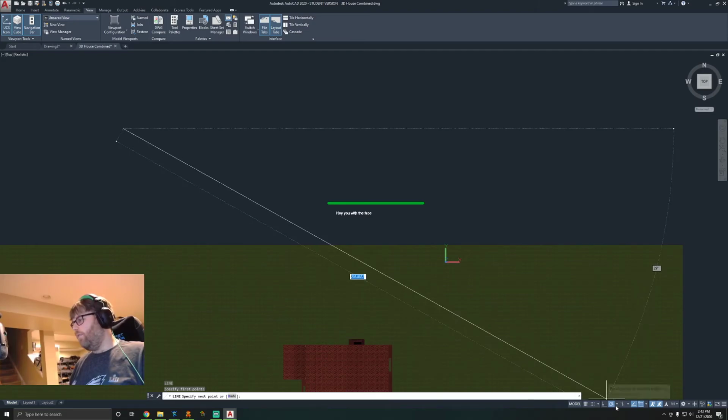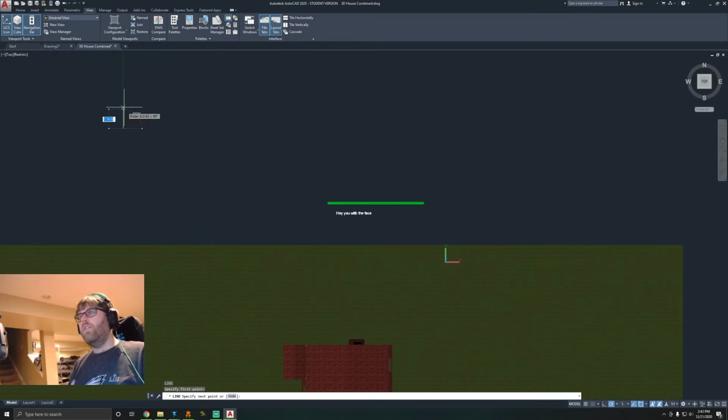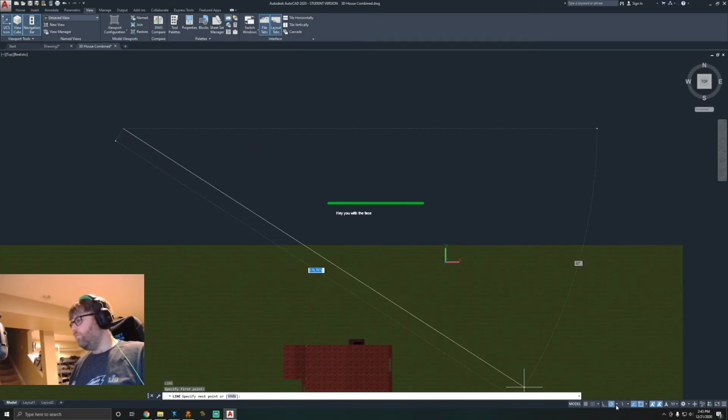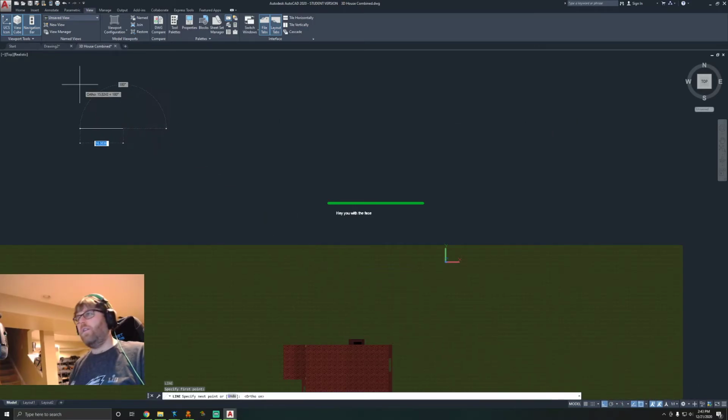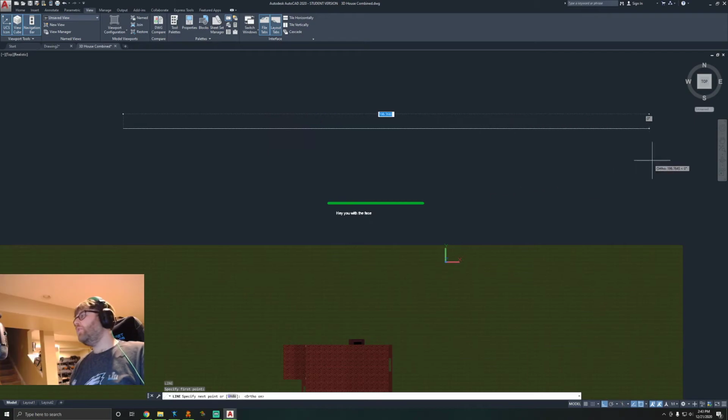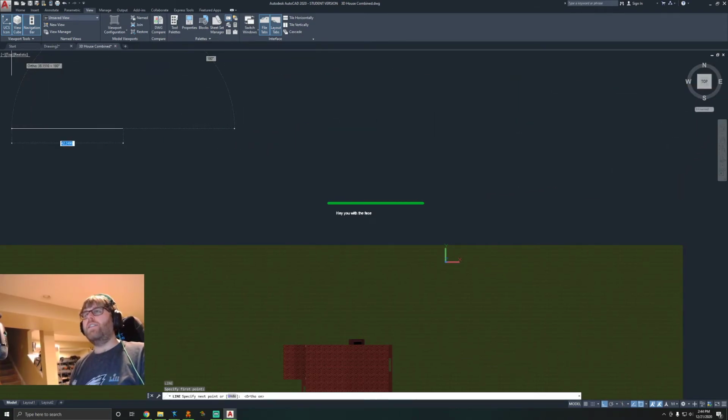So if I just snap this to 90, it'll do this. No, nope. There we go. It'll look like this. And you're like, I want to draw this at an angle. What the crap is happening? And that generally has happened when my students have used the view cube instead of this. CAD gets confused.